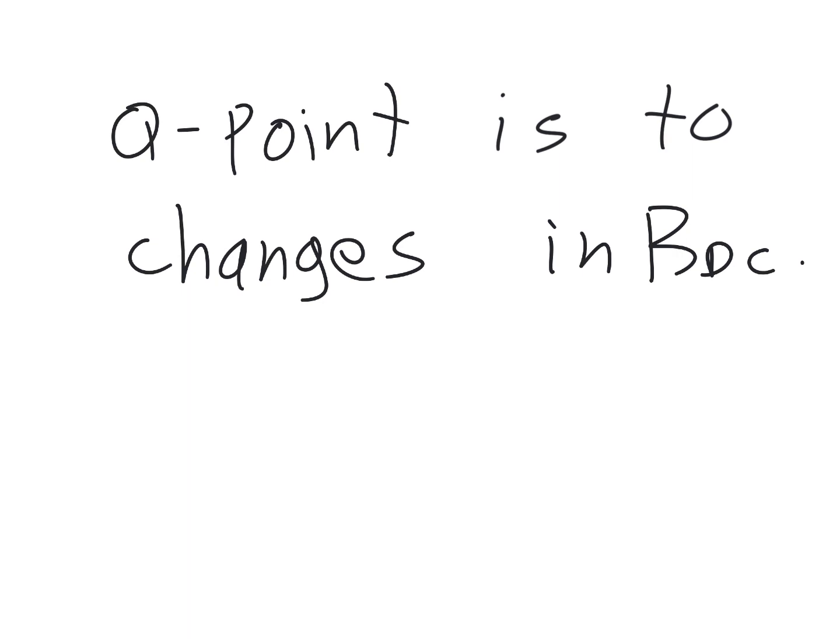When you compare the emitter bias to the voltage divider bias, the key point is that it's more stable, not a lot more stable with the emitter bias. But anyway, the voltage divider bias is more popular because it uses a single DC bias supply. The emitter bias requires a split power supply, but that's not really a problem anyway.